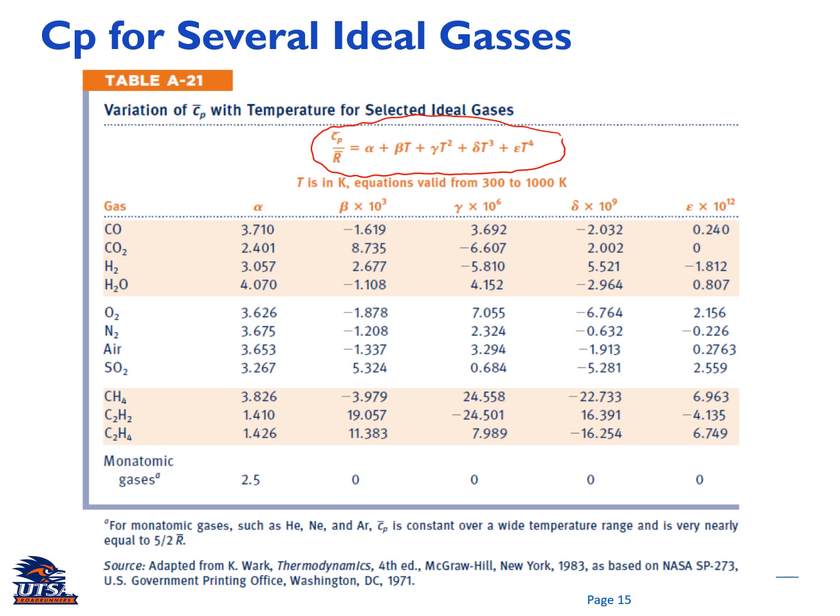So in the first row here, we have constants for CO, and then CO2, and so on. The data representation for Cp in terms of the polynomial function here is very useful when you want to calculate Cp and use it in programming.